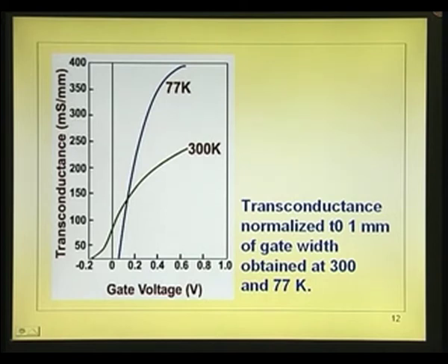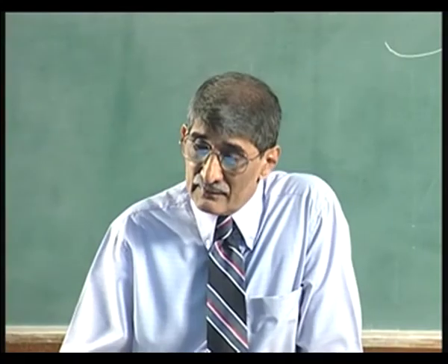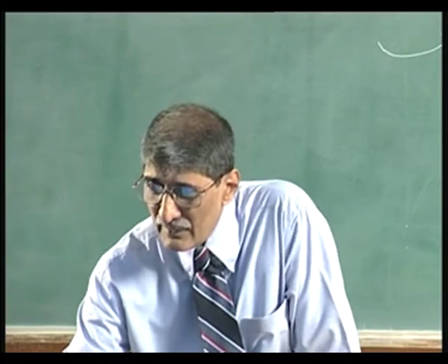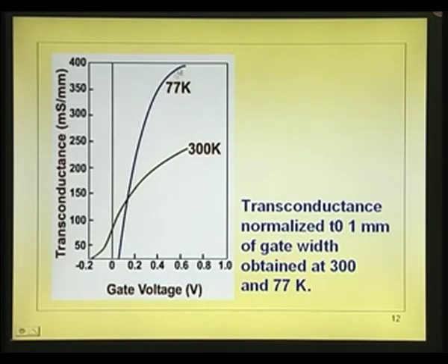In the case of MOSFET also you will see that, because of the high field effects in the vertical direction. Okay. And in this case there is an added effect, that is we are talking of this portion, a slight tapering off, or the rate of increase of the transconductance reduces.